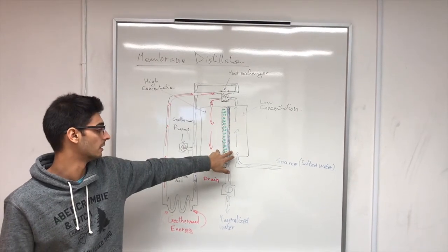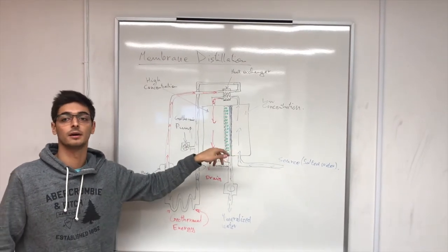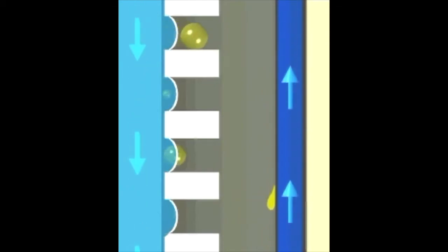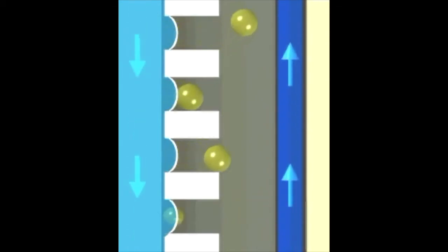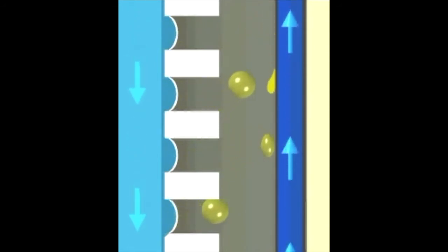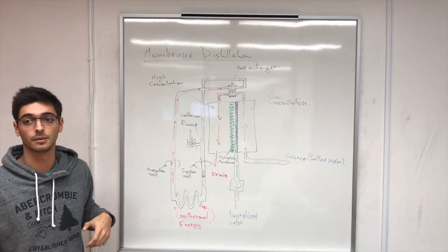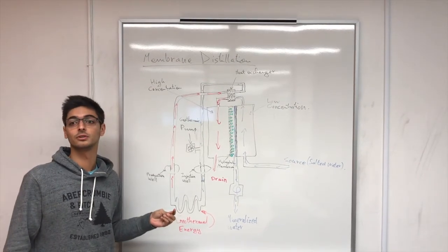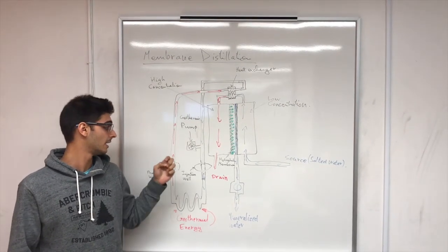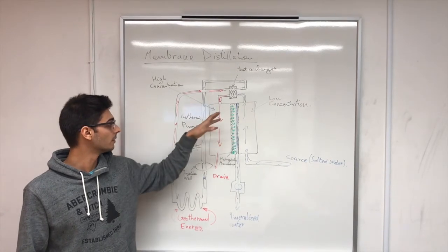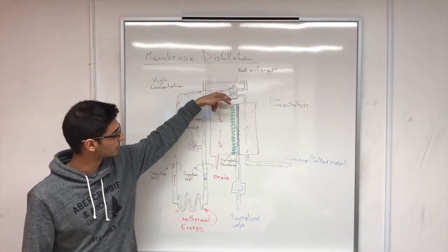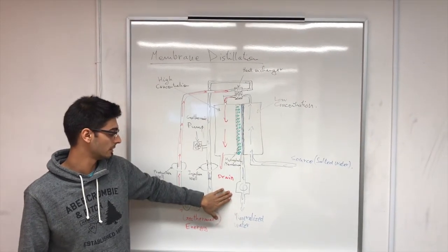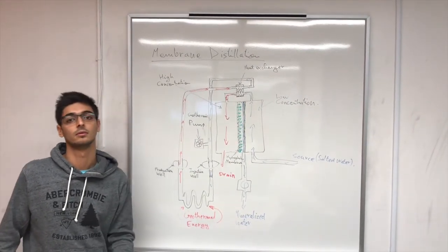And what happens here is just osmosis. The way it works is the hydrophobic membrane displays a barrier for the liquid phase, allowing the vapor phase to pass through the membrane's pores. The driving force for the process is given by a partial vapor pressure difference, commonly triggered by a temperature difference. After that, the drinkable water is collected on this membrane and goes through a mineralizer, and then it becomes drinkable.